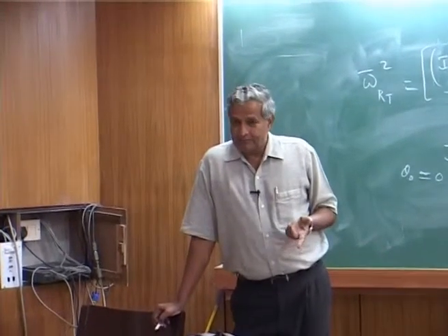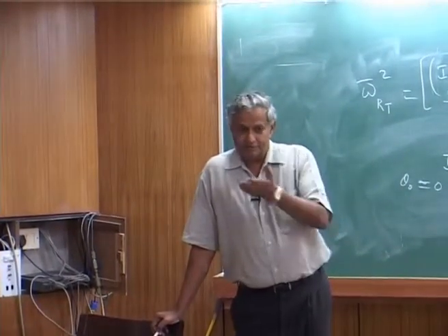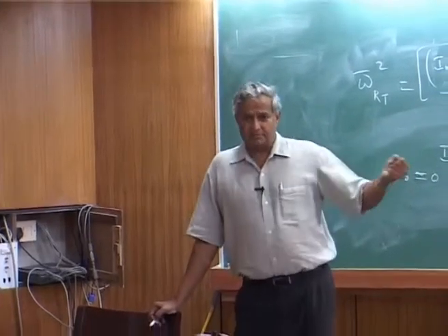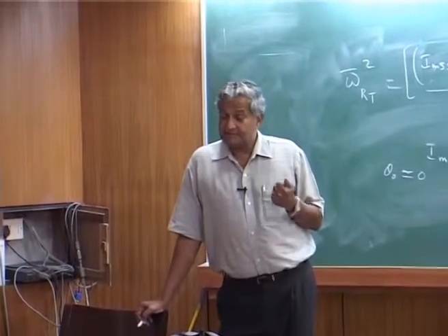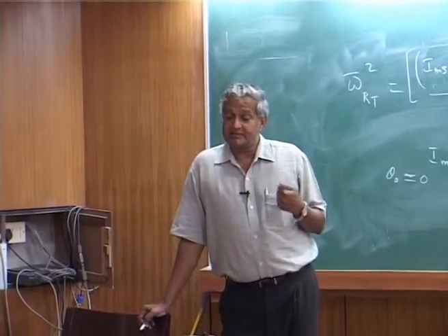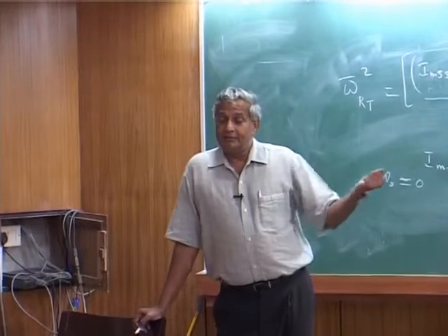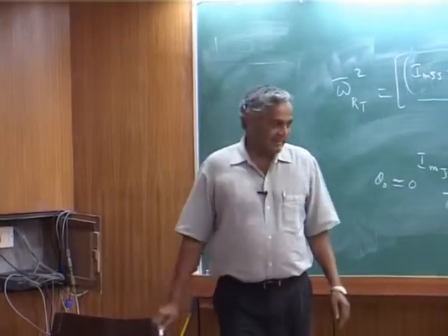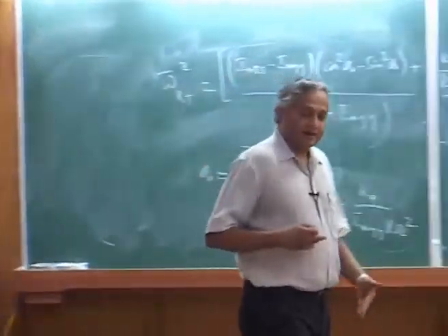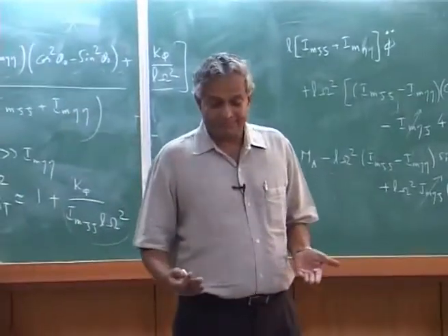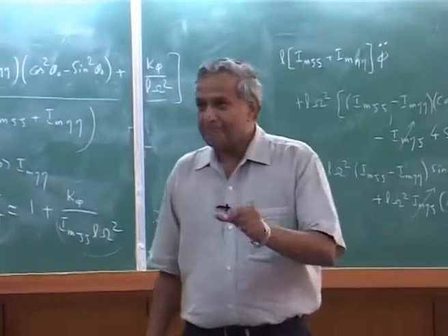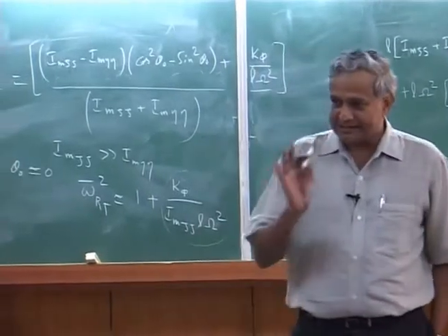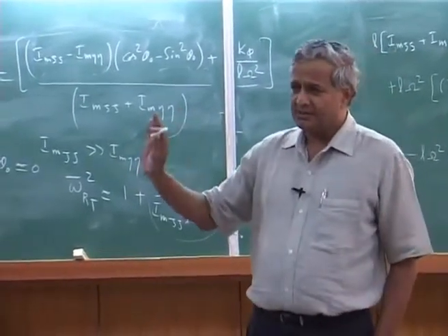Okay? But the question is, what if you have a centrifugal force? What do you do? There will be an axial deformation. Yes, it is there. But then you have to include the axial frequency. Okay, axial mode. Now, treatment of the axial degree of freedom itself has several approaches. One is you make it a rigid blade approximation.